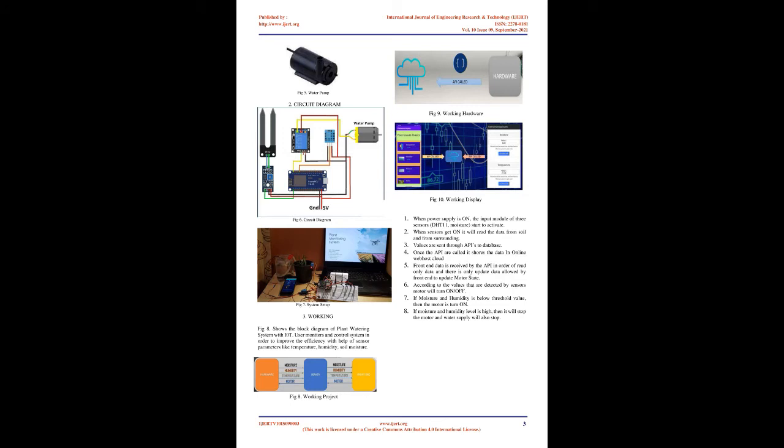Proposed system. The system is a combination of hardware and software components. Sensors. Moisture sensor. A soil moisture sensor is used to detect the moisture of the soil. This sensor is made up of two pieces, the electronic board at the right, and the probe with two pads, that detects the moisture content of soil. How does it work? The voltage of the sensor output changes according to the moisture level in the soil. When the soil is wet, the output voltage decreases; when dry, the output voltage increases.